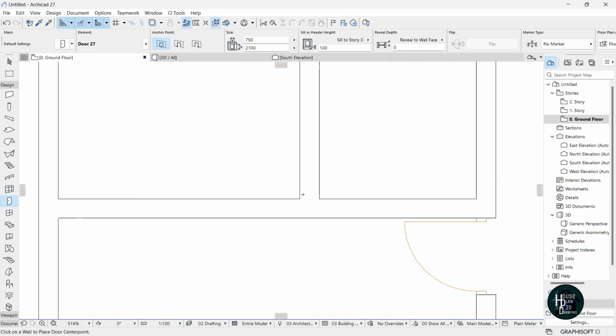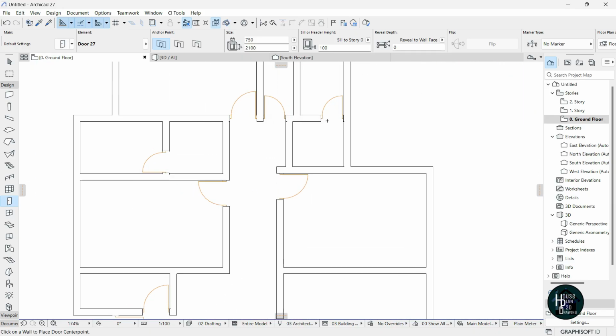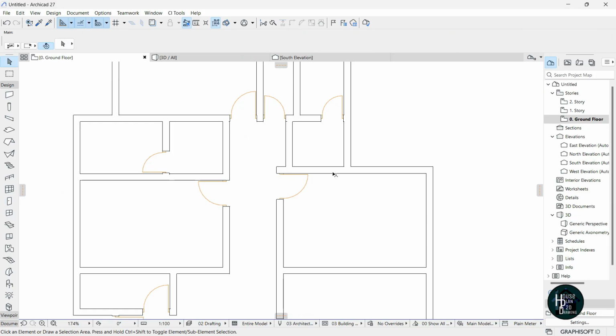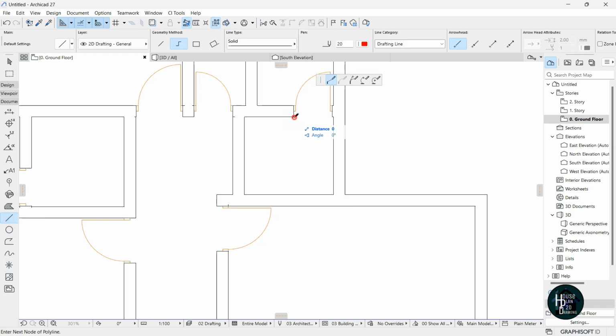We also need the door here too, so you want to come open the door here, just click. Okay, now we need there to be an opening here and also an opening here. So what you want to do now is come to the document section, click on the line tool here, click on this edge here, move it down, double click. Once you do that, press Ctrl on your keyboard, cut out the side. Okay, now press escape again, click this line and delete it.